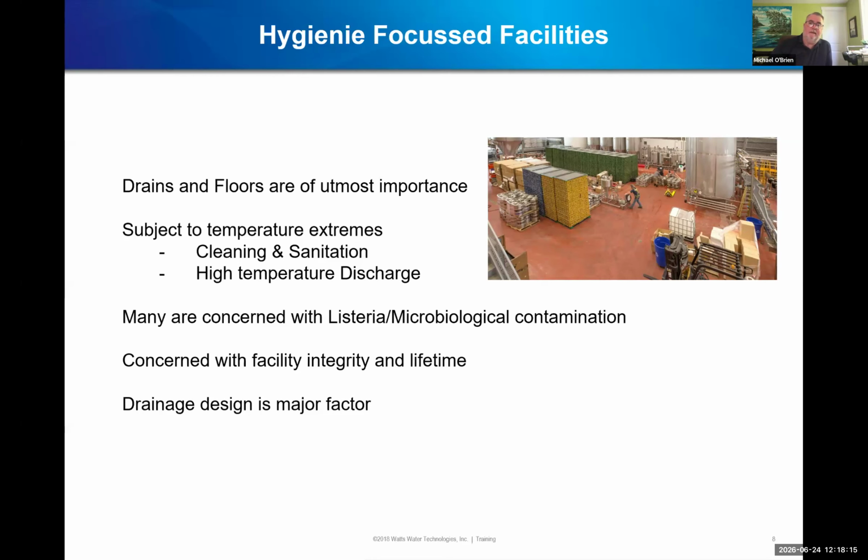What actually happened is that because these were older facilities and did not have stainless steel drainage, the dissimilar materials in the floor expanded and contracted at different rates, and there was separation of the trench drains from the concrete floor and the flooring material. There were cracks radiating out from the corner, so all of the food particles found a way to get into those separations of the floor or those cracks in the floor.